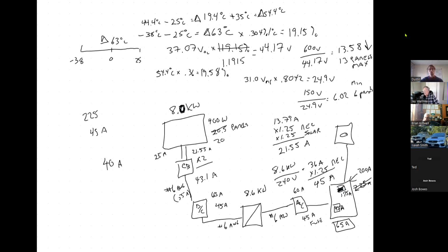But are you saying, I mean, you could swap out the service panel for sure. You could put in a more robust service panel and then it's not an issue. I could put in a 400 amp service panel and not change the 200 amp service from the utility, and then I've got lots of capacity. What we're talking about is the bus bar rating of this piece of equipment.